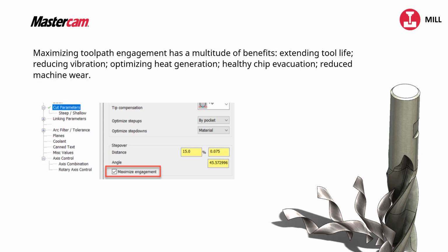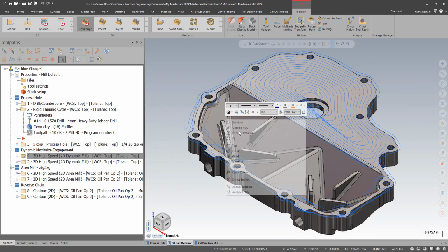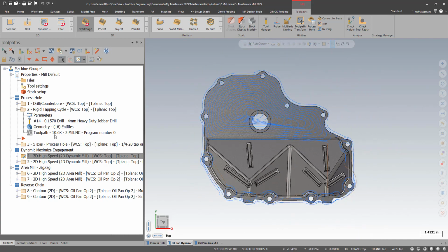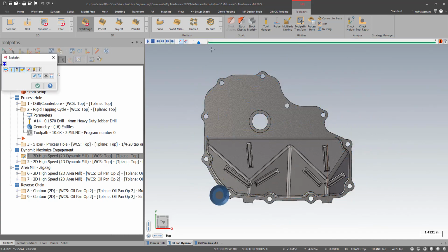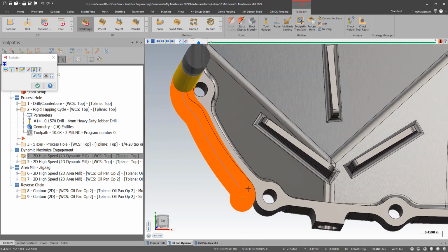So in previous versions of Mastercam, when you do dynamic toolpaths, it basically slowly engages into the material. It takes a while to get into the full step over. So if I backplot this one, turn off my holder here, try my quick verify. If I tilt this a little bit, I can see that edge. It takes a little while. I'm not really at full engagement, I'm at 20% step over, until somewhere over here before I get full engagement. It slowly engages in the material.